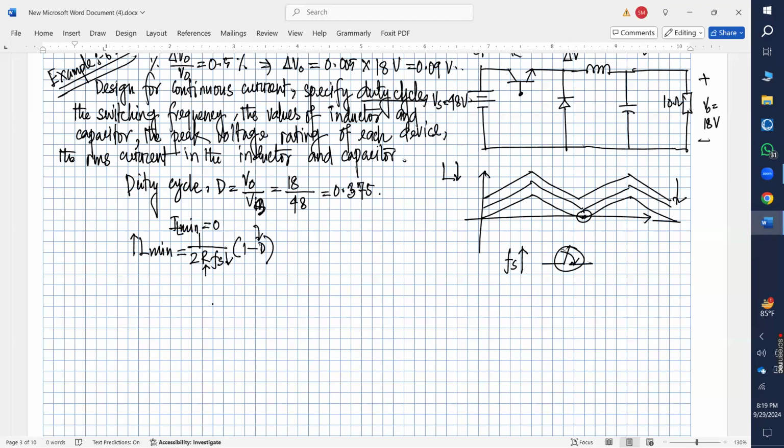So are you getting what I am trying to say? Can you please explain it again? Yeah, so what is happening here? Suppose, as I said, if you put too much switching frequency, here at that transistor T1, this transistor will turn on and off too fast, and as you turn it on and off too many times, there will be a switching loss across the device, and this switching loss is dependent on the frequency.